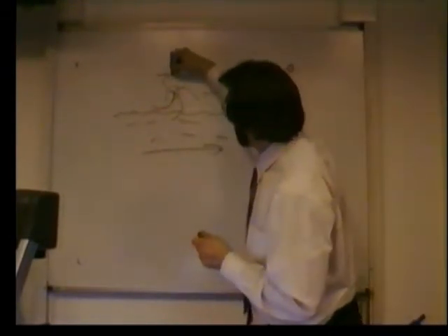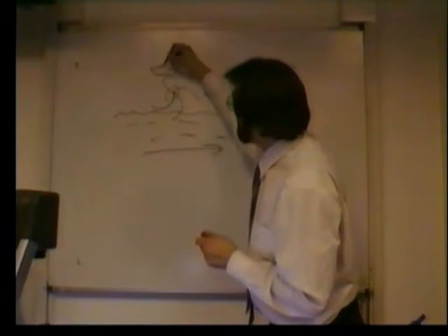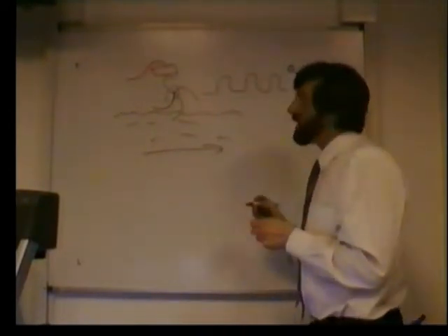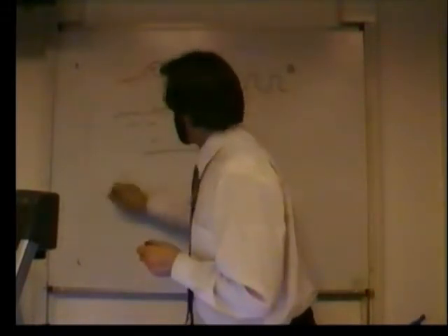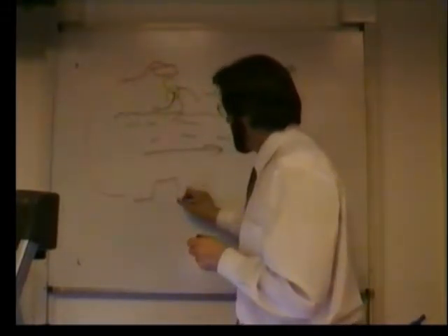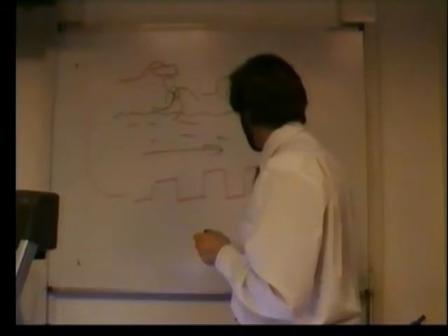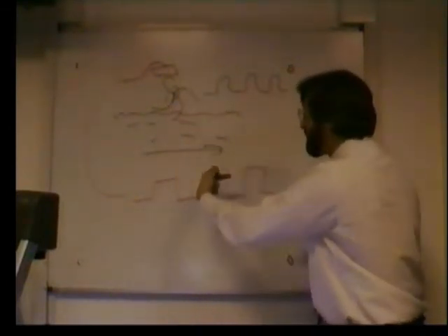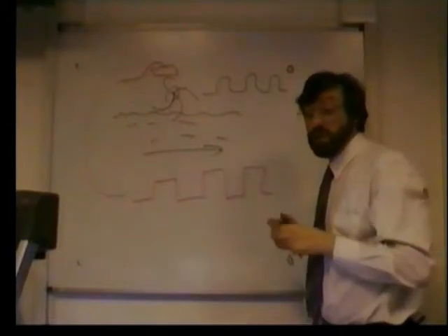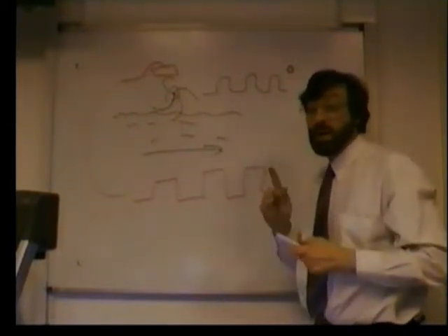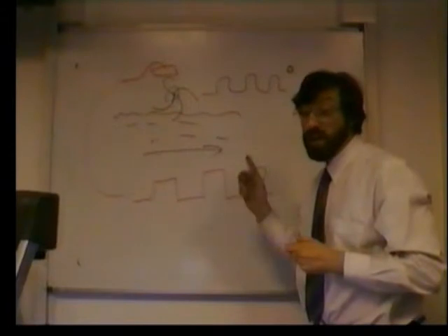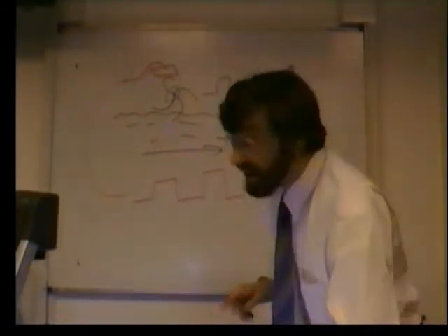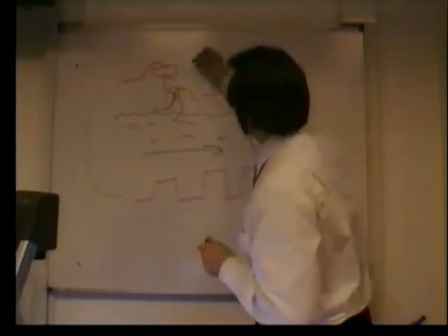If we were to place above it an electromagnetic sensor that goes off to our computer, what we would have coming out of our sensor is a pulse train every time one of the vanes of the wheel rotates. So if we can count the pulses into our computer, we will know exactly how much water is flowing through our shower system.